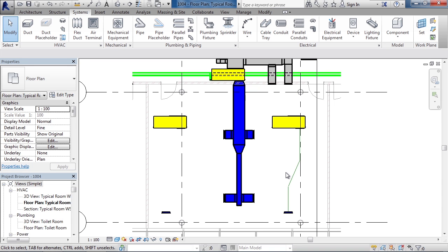It also lacks information for insulation or lining, whereas a regular duct would have that information. But as far as placement, if I'm manually clicking points, it is placed the same way as a regular duct. So in this lesson here, we're going to look at placing a regular duct from a diffuser to our air handling unit. And we'll use those symbols on our very left.